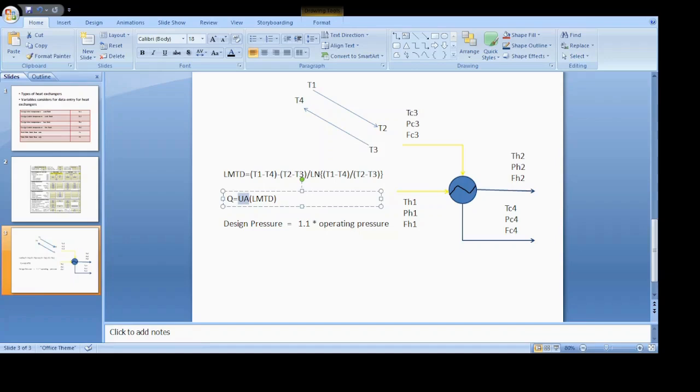So here, first of all, check the pressure spec and add the mass flow rate at the inlet of the stream, add the composition for the particular stream for the shell side and tube side, put the outlet stream on a pressure spec, then start the simulation, then stop the simulation, check the mass flow rates are correct as per the HMB, check the temperatures for both the shell and tube side are as per the HMB, check the duty.